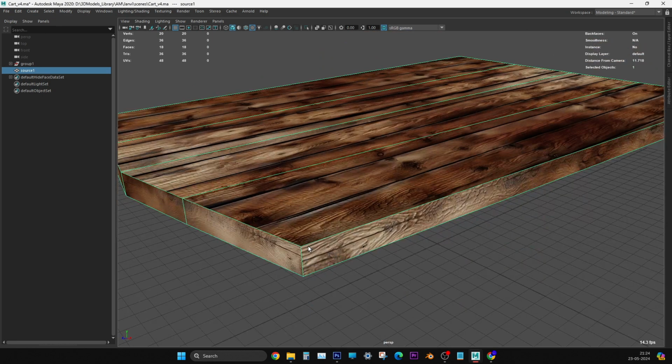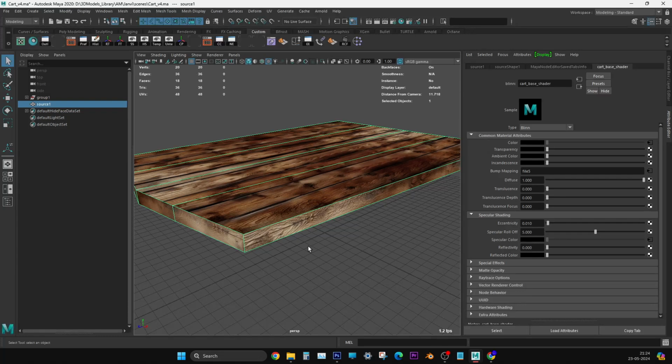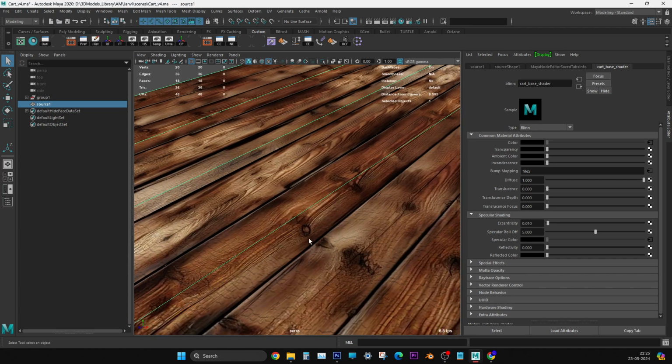That day you asked how to create a bump map. What is this bump map? This is how we should apply it. This is how we should bake the color map into a bump map. It is not like going to Photoshop and painting in black and white, all that. No, you have to bake it, from whatever texture you have painted in color.